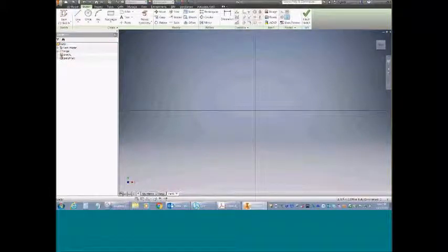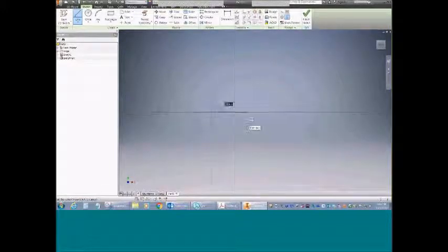I think I'll start with the line command, so I'll just use the command wheel for that, and I'll start to drag this out here a little bit. When people are coming from the world of AutoCAD into this class, the first thing they want to do is go back to those old habits where if I drag this out, I have a heads-up display. I can type in the distance I want that line, and that's not necessarily a bad thing, but I think it works a lot better if we just get the sketch up there at about appropriate size with all the elements of the geometry that we need, and then we go through and do the constraints and then the dimensions.